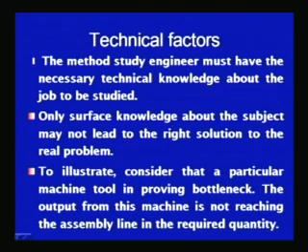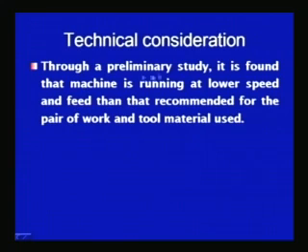That is why we take up this example to clarify the importance of technical expertise for carrying out method study. Like if a particular machine tool is proving a bottleneck and the output of this machine is not reaching the assembly line in the required quantity, then a preliminary study indicates that the machine is running at lower speed and feed than that recommended for the pair of work and tool material used.